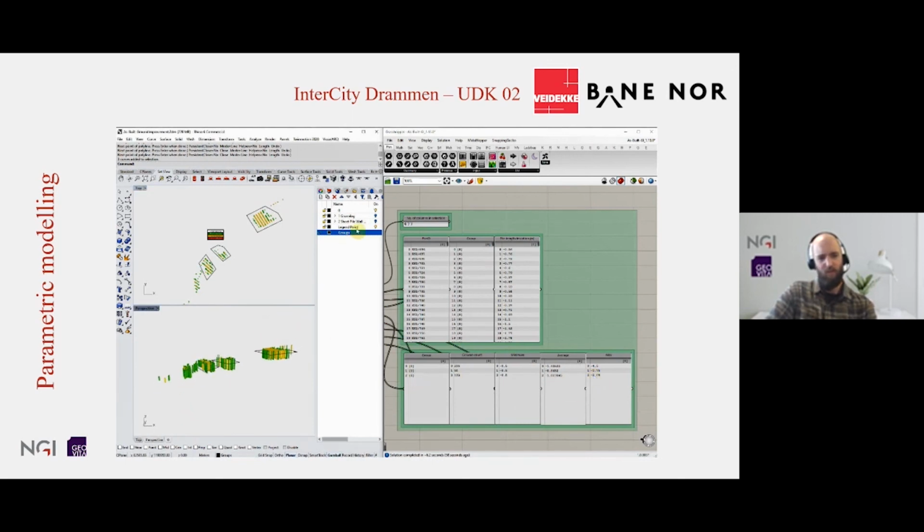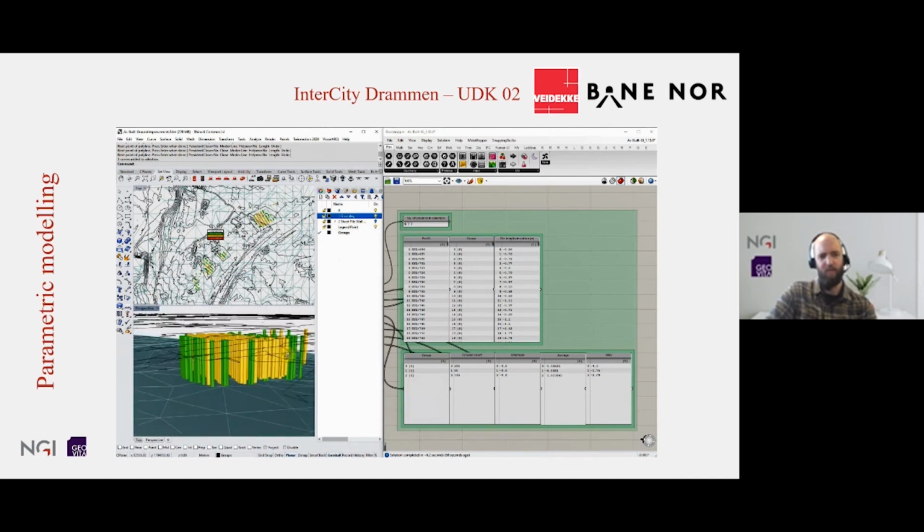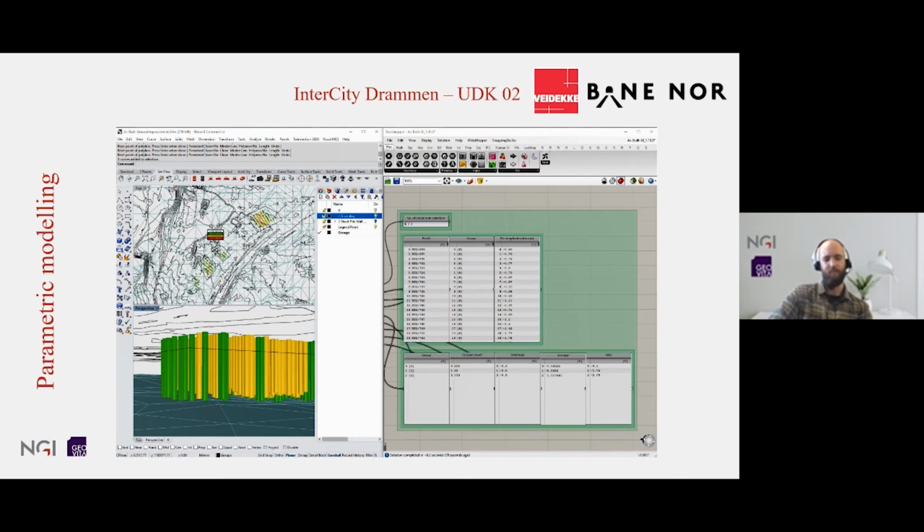The reason for the columns being short is, in this case, the moraine surface being slightly higher than what we predicted during the design phase. So this will not pose any issue for further construction, but it's good to be aware of this when you move on. There can be other issues that might not be acceptable.